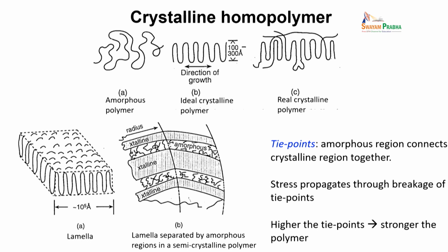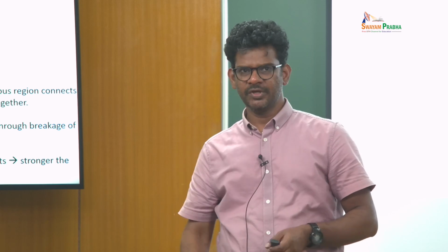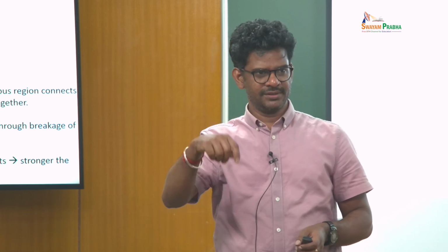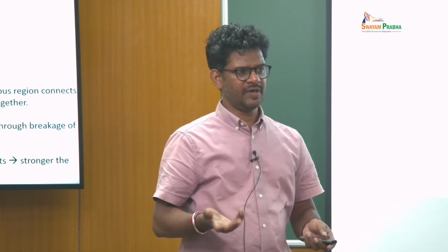What you generally have is this kind of polymer where you see that, on average, there is some order, but there are also a lot of defects. There are chains that are making an extra loop here, right, and you see that sometimes this one is actually not participating further, and another chain is taking part in the repeating units. Okay. So this kind of looping structure of the chain over and above is very typical of a polymer crystal.